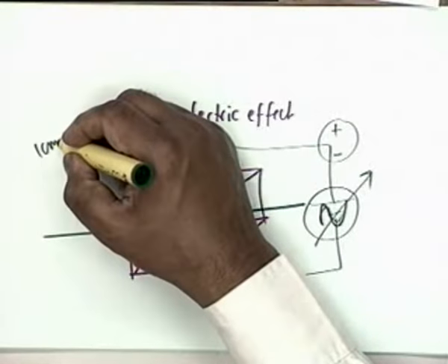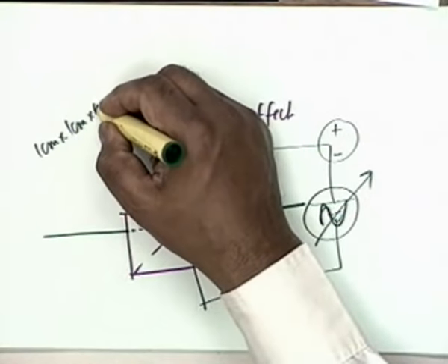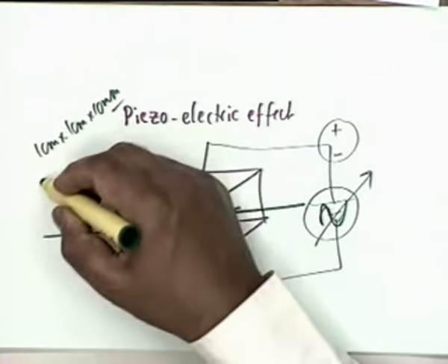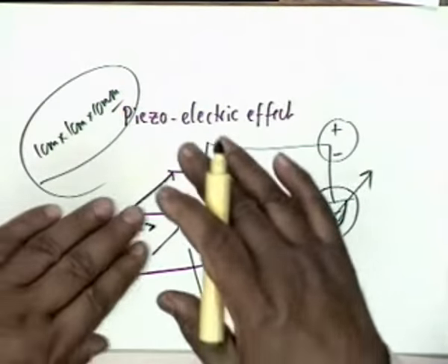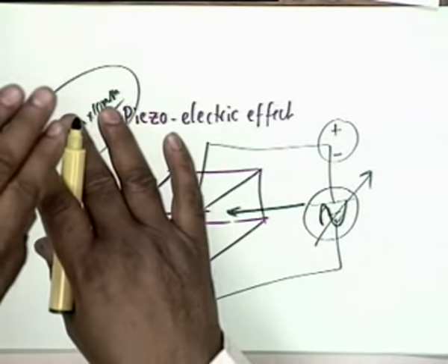However, you cannot observe this mechanical resonance with naked eyes. The crystal itself is very small, typically 1 centimeter by 1 centimeter by 10 millimeters. This is a typical dimension. In order to apply a field, because this is a dielectric, you have to have two faces coated with metal from which you take the terminals. If you do that, obviously you create a capacitance. A dielectric material between two metal plates is a parallel plate capacitor.